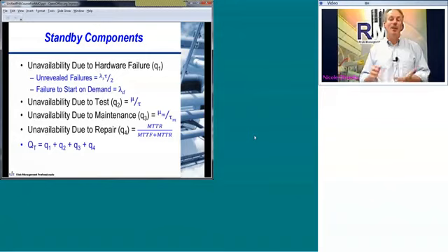If you've got a standby failure rate, lambda sub s, given to you, you can identify the unavailability of that equipment with 1/2 lambda tau. Also, equipment reliability data books, especially for relief valves, will often have a failure to start on demand or failure to open on demand.